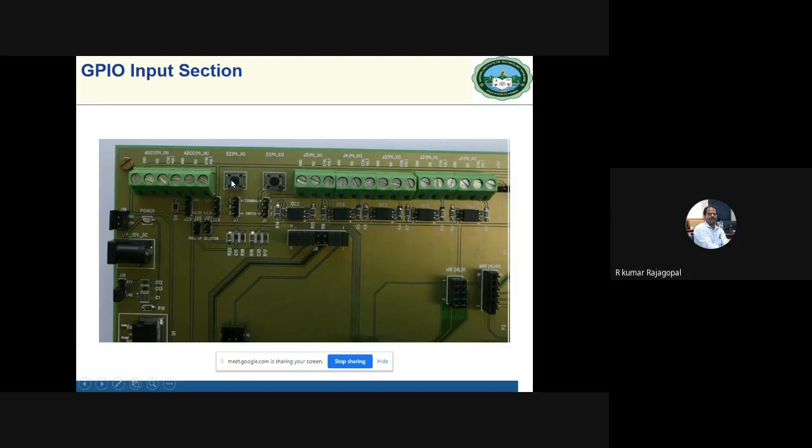In this case, the switch is connected to a 32-bit processor, which supports two edge enabling, rising edge and falling edge, for interrupts. Usually you can use either edge or both. Assume one edge, the rising edge. When the interrupt signal occurs, the corresponding handler is automatically executed.